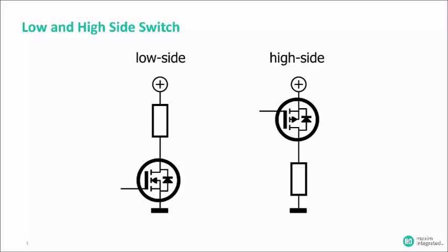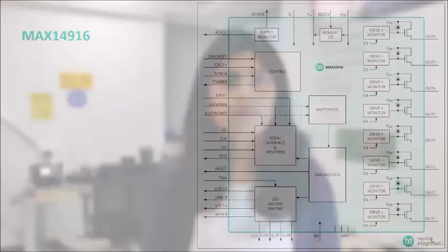When the transistor is connected between positive voltage and the load, this configuration is called the high side switch, since the transistor is switching the path to a higher voltage than ground and is sitting on the high side of the load. In circuits where the load is connected to a single supply voltage, such as a car where the battery voltage is fixed and the body is grounded, the output can become grounded. In such applications, high side switches are used as they can detect abnormal conditions such as ground faults.